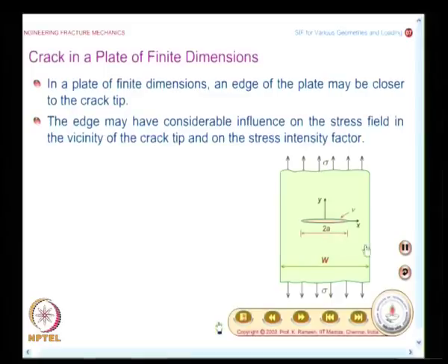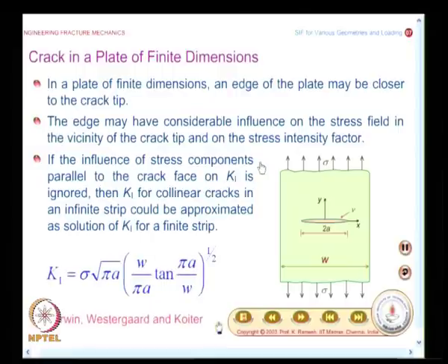And in those days, when Irwin developed this, this was the specimen they used for finding out the fracture toughness also, you have to keep in mind. So, this was used for material testing. They needed expressions which are analytically reasonably good to find out the value of K. And what you have to keep in mind is, when I have longer and longer cracks, the edges will have a considerable influence on the stress field. So, the solution needs to be improved further, but this is how initially the solution was looked at.